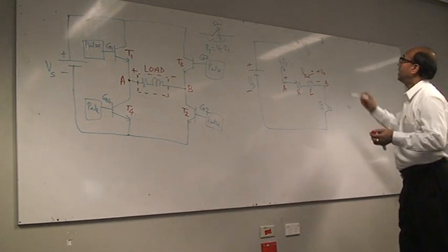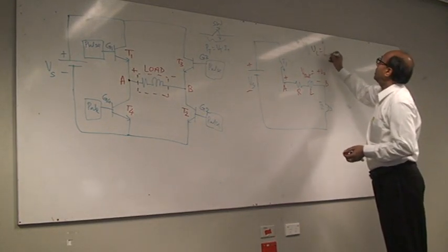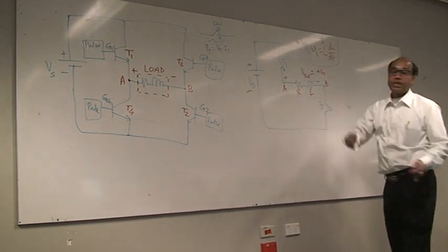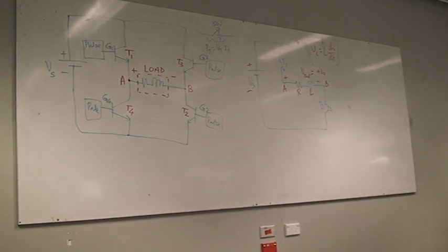So what happens if you do that, then the inductor will generate a voltage which is L di/dt, and that's such a big voltage that it can actually ionize the air. And you have seen that when you switch off some appliances at your home. You have seen sparking? Have you seen or not?